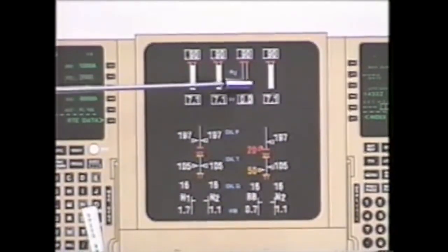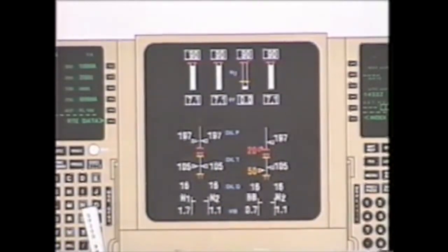This line on number 3 engine, which is shut down, indicates the minimum fuel on line, which would disappear after the first officer brings the fuel lever up to run. Oil quantity, the minimum oil quantity for engine start is 18 quarts. Other synoptics again available would be fuel, hydraulics, ECS, gear, and so forth.